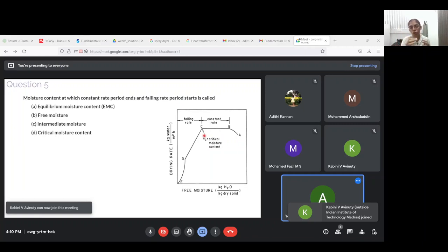And since you have a lot of water vapor at the initial stage, you will actually find that the rate is constant. It is entirely dependent upon your temperature and your outside pressure and the evaporation rate, and on nothing else. So at this stage, when you have an abundance of water vapor on the surface, you will have a constant rate. After a certain point called the critical moisture content, you will see something called as the falling rate period. This is because whatever was on the surface of the particle, that is whatever water vapor was on the surface of the particle, has now dried. So whatever is now inside the particle should come onto the surface, and then that should be evaporated.